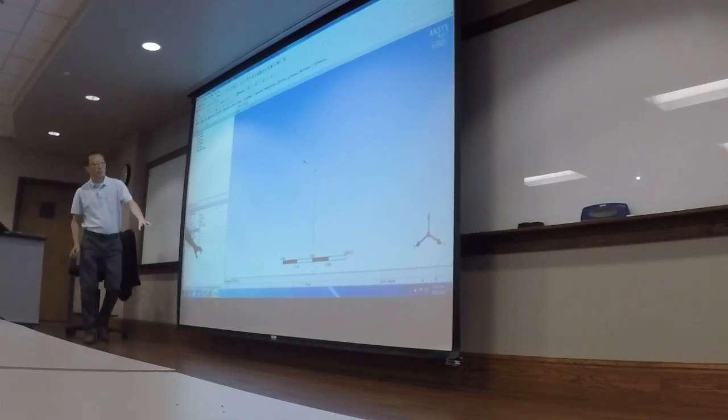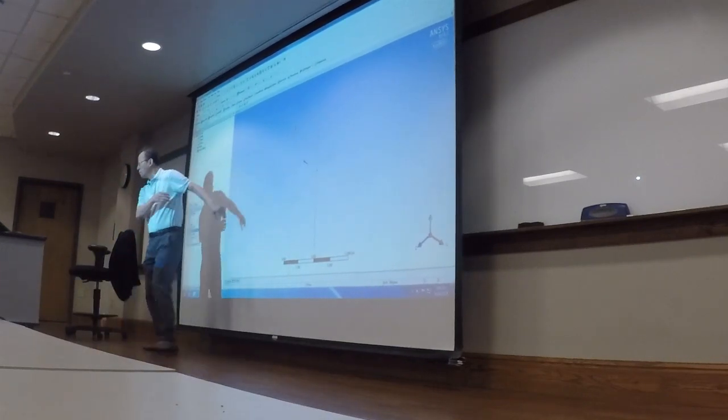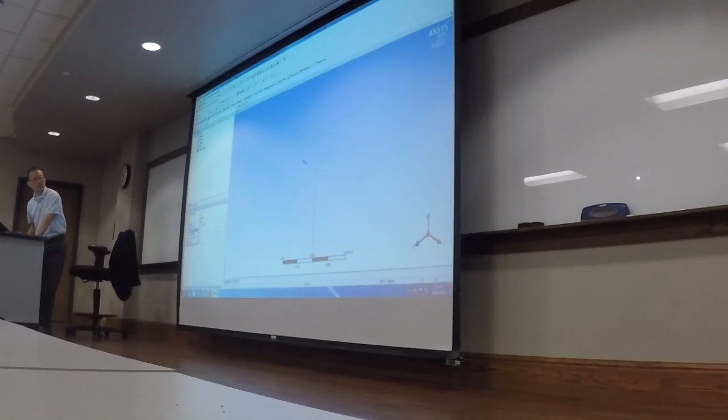All right. So we create a new plane back in the x direction, 4 inches. Generate, and on plane 4, click on plane 4, we're going to have a new sketch. Click on new sketch, enter plane 4. New sketch, plane 4. Then we do just like what we did for the tutorial.